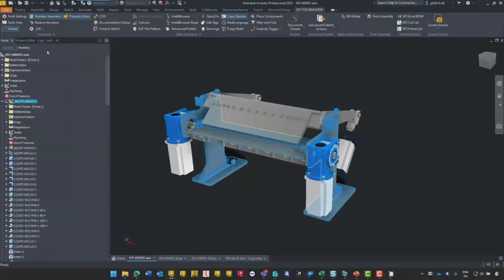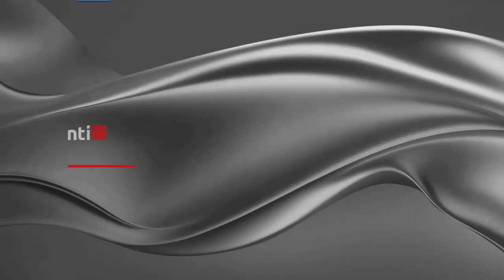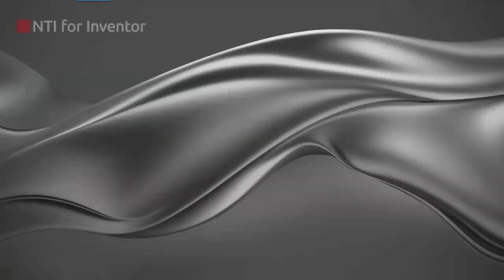And I'll just use an NTI function, open newest drawing. So if it is a newer drawing local, it will open that. And if it is newest in the vault, it will open that. So also a little function hidden in the tool, or in the NTI for Inventor.